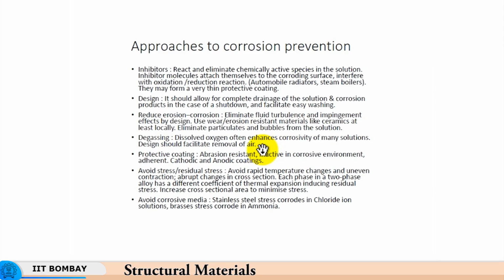Another way is to remove oxygen. We have seen that oxygen is the culprit. It is the one that creates many issues when dissolved in acids or even fresh water, sea water, and so on. So dissolved oxygen enhances corrosivity of many solutions. We have seen that in sea water, if oxygen is dissolved, it accelerates the corrosivity, it enhances the severity of the corrosive attack. So we need to therefore degas or remove oxygen from the solution or the liquid that is going to come in contact with the product.